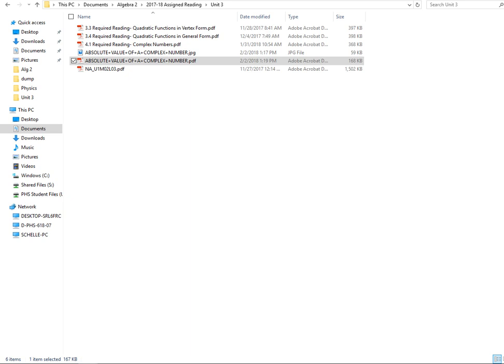So 6% is kind of the maximum they would ever let you do, because that's the point where they assume something. So we could figure that out. Okay, here's our plan for Monday or something. If that's what they're saying is the maximum angle, we have to be able to calculate the minimum coefficient of friction they're assuming, right? It would be the one that would just allow a car to stay without slipping on the banking angle. Well, you can ask, but we've got to figure it out on our own.